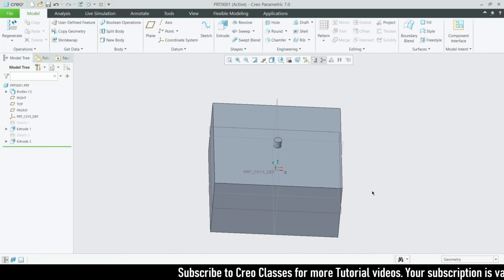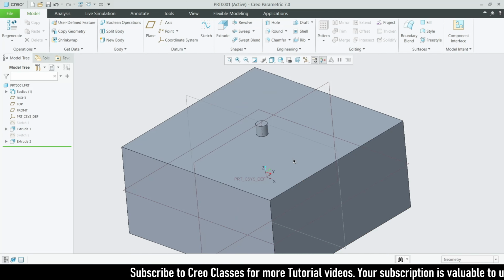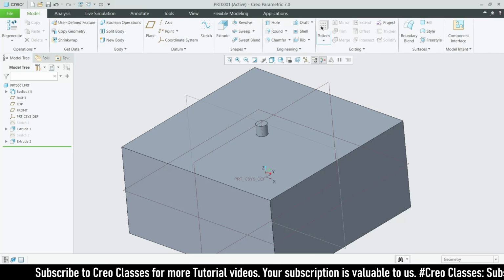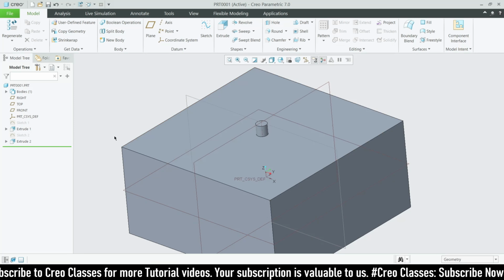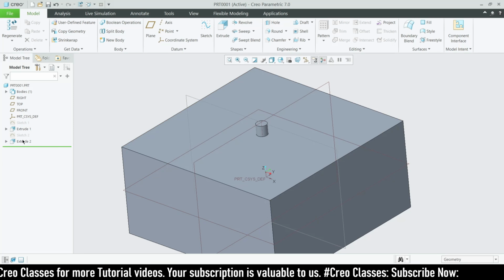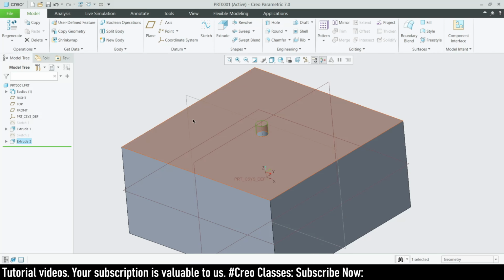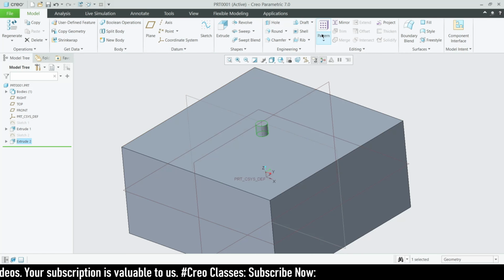Yeah, so first of all, what is the pattern tool? We can see the pattern is not highlighted right now because we just have to select the part on which we should use the pattern tool, right? So we have to select the part which we are going to use for the pattern tool, then we have to go for the pattern.